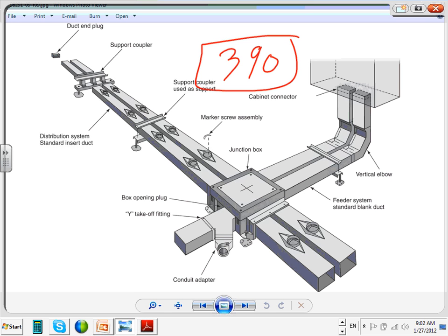What you do is you use channels assembly. You use 2 channels. Anybody knows why 2 channels here? Now remember, all this will be buried in concrete. Because one we can use for high voltage and one for low voltage, right? As in communication and data, and the other one for the high voltage. So you build all these channels, guys, 2 of them going, in this case, vertical elbows. Okay, so let's assume that there's a barrier here between them. You have your J boxes, you have device boxes completely embedded in the concrete.